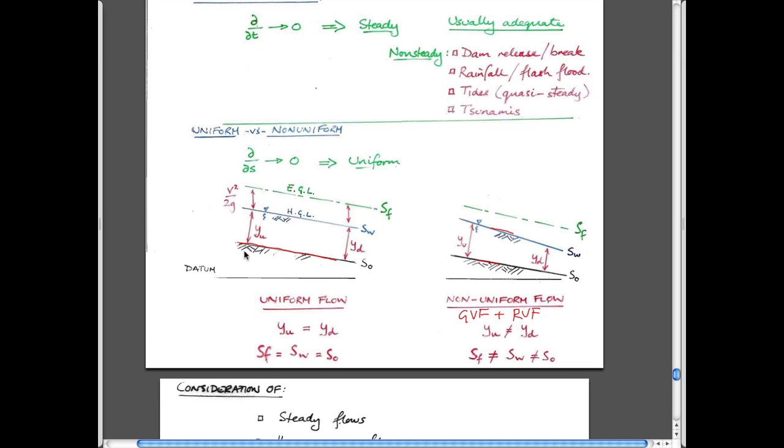So it's a single line that's oriented in some orientation. But most importantly, the slope of the water surface is exactly parallel to this. In other words, the slope of this surface and this surface have to be the same. If we think of that in terms of the terminology that we've used for Bernoulli's equation, if you remember, we talked about the hydraulic grade line as being the sum of the elevation.